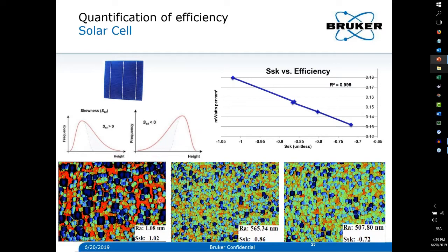If you look at the 3 different surfaces of this polysilicon, there is some kind of wet etching, chemical etching, that helps to create the structures. So there is a way in the process we can control and get either this type of surface or this one. The point is, due to the variability of polysilicon and the variability of the wet bath, there is a need to control the final state and do a further etching or not.